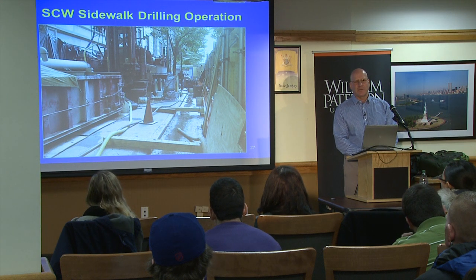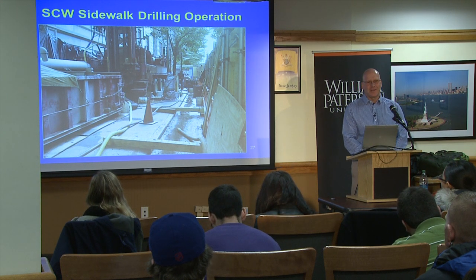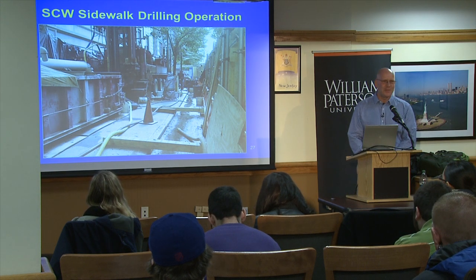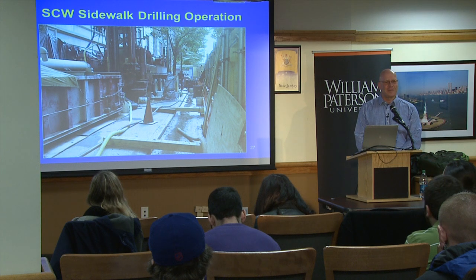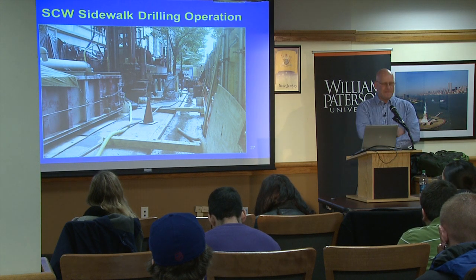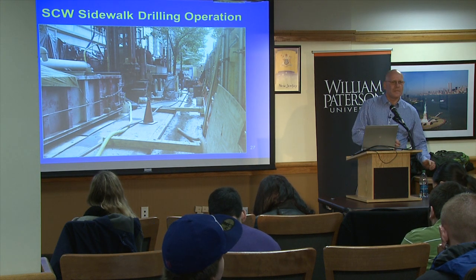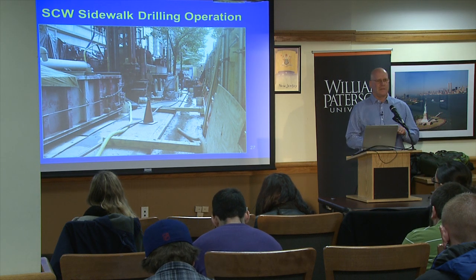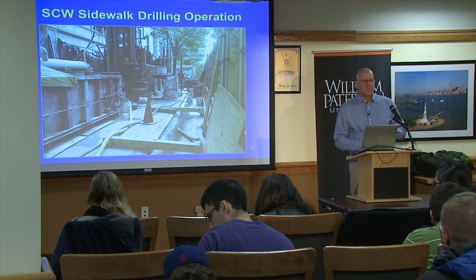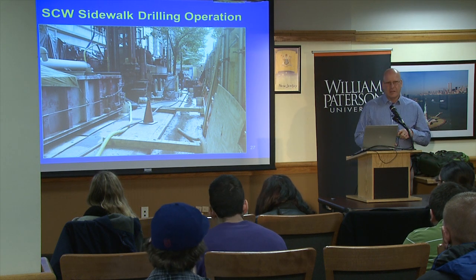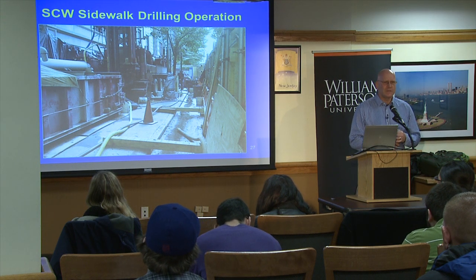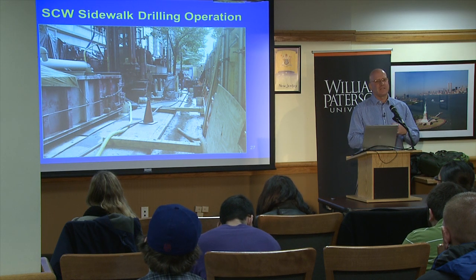Yeah, so this is unique. It's not every day that someone has $400,000 to shell out on an air conditioning system, but there are sometimes those that happen. What's up? For the standing column wells, when they're at a depth of 1,500 feet, how long does it take to drill something like that? Generally, the drilling portion, if there are no problems, and there were always problems, is 2 to 3 weeks, but the entire system may take double that.